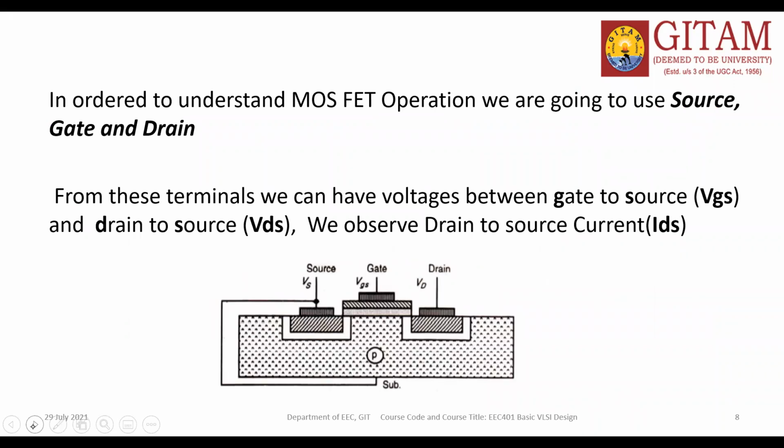Okay, so here the relationship between VDS and IDS, as I mentioned previously, is that IDS is a linear function of the VDS value. That means something like this. So a linear relationship exists, or this linear, or this linear, or this linear. What are these curves saying? They are for different values of VGS.